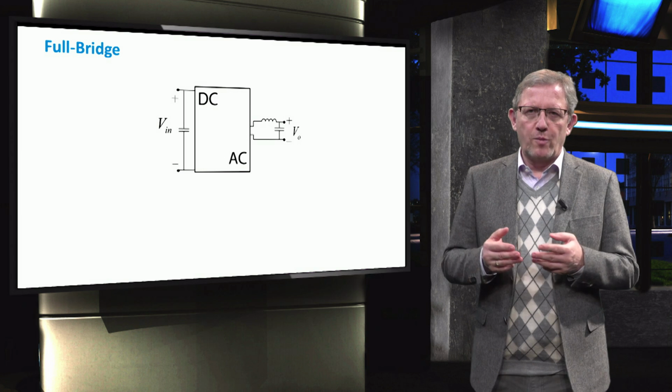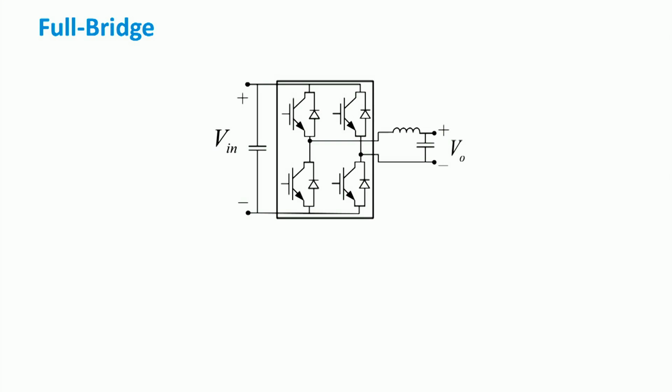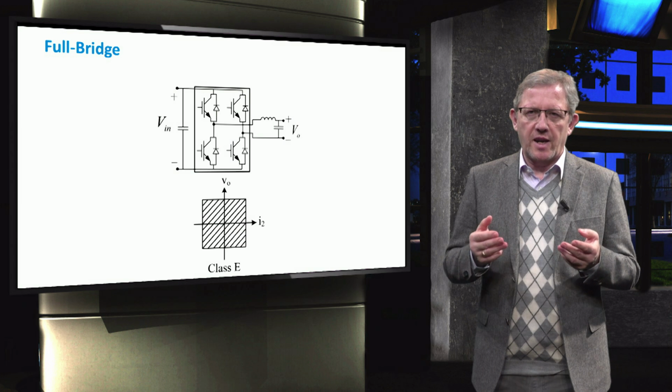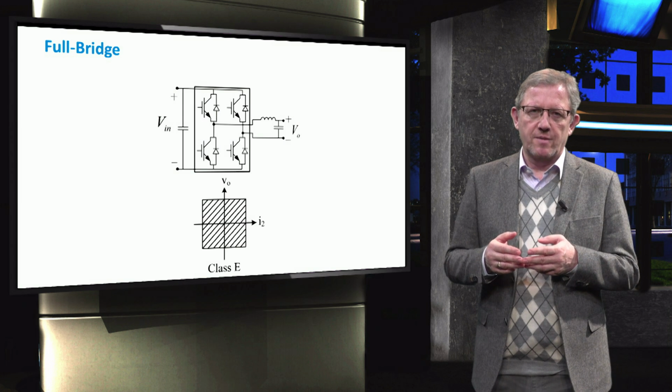We analyze a full bridge DC-DC converter. The full bridge DC-DC converters consist of the 2 legs and 4 switches. Thanks to 4 switches, the full bridge DC-DC converter is able to support both positive and negative voltage outputs that can be used as 4-quadrant. The bidirectional current flow becomes possible due to the diodes in antiparallel with switches.